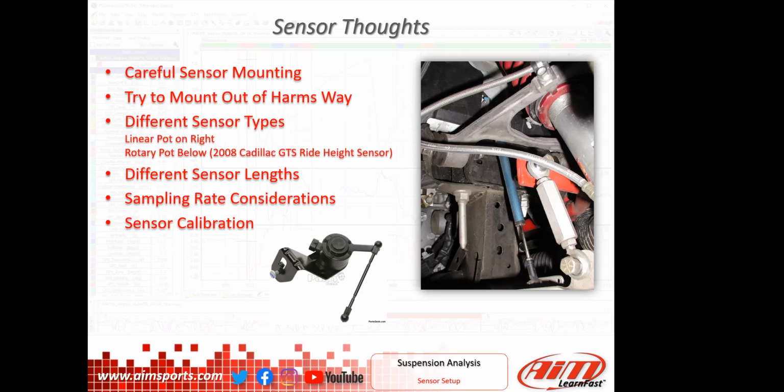Suspension is one that we just have to capture at a lot higher rate, in order to see you catching the curb or hitting a bump, or make sure we see the roll of the car. And then we have to be able to measure fast enough and with enough of the travel to get some of these histograms and the velocities and some of the stuff we're going to talk about here in a minute. Typically, the data we're going to look at today was sampled at 100 samples per second. Most people will tell you that's a little bit light, and I probably would agree with that.